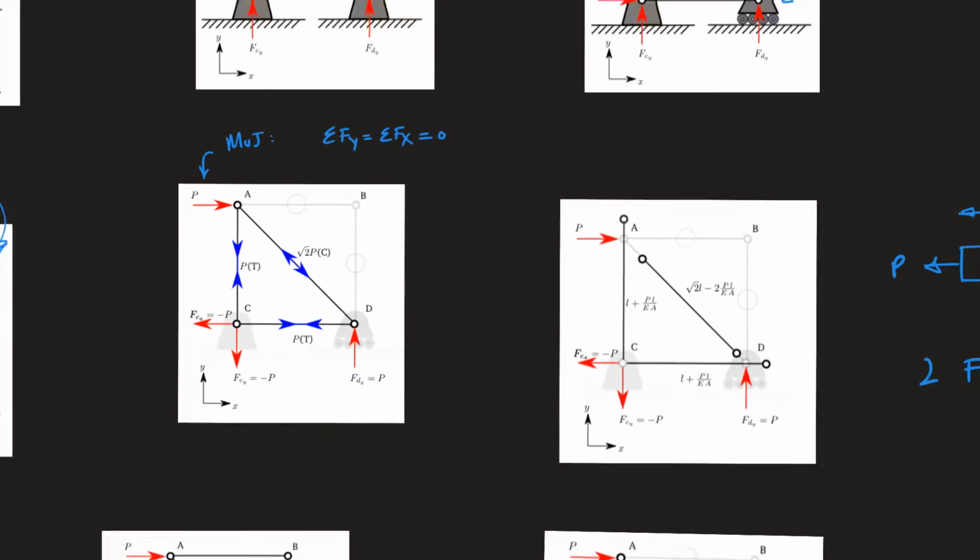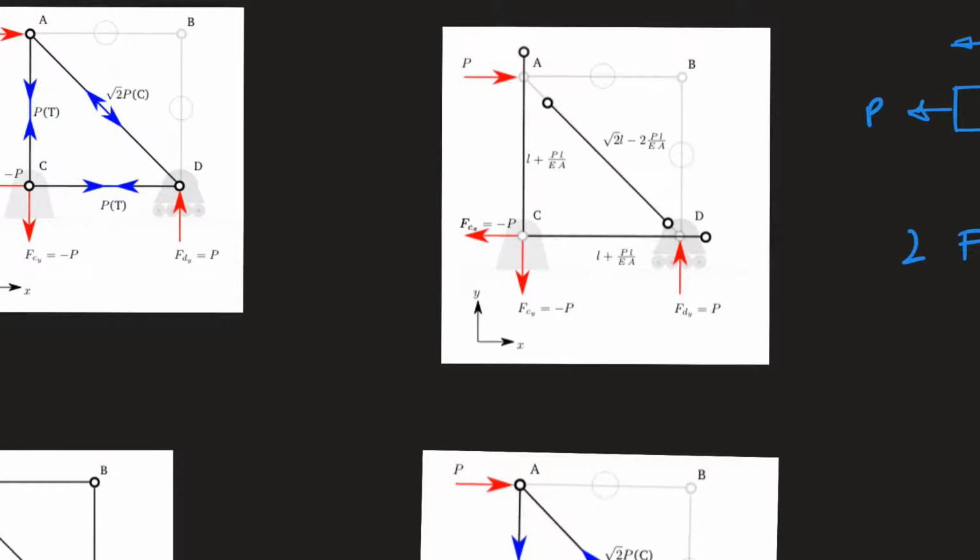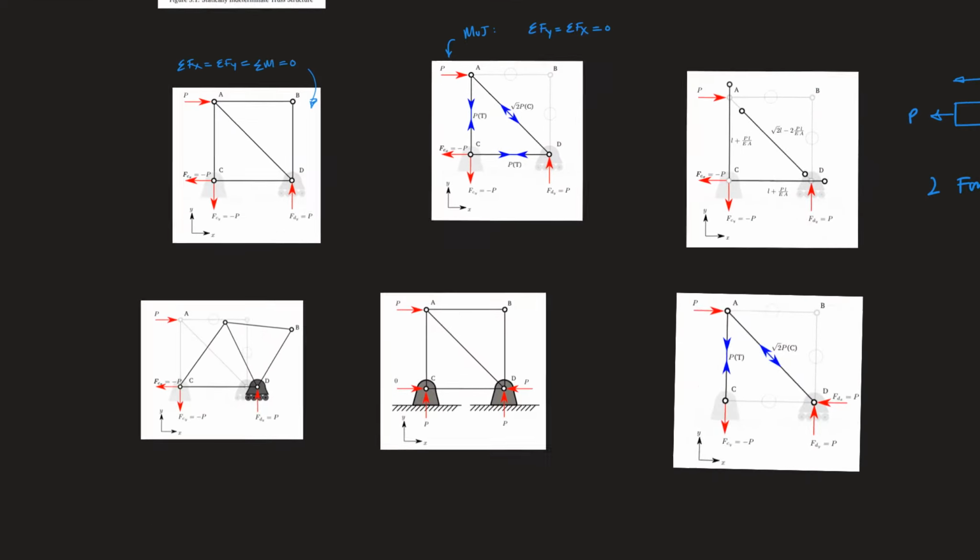So for this member here, we could ultimately unpin all of these members, and then we could work out what sort of triangle they've got to be to go back together. And in the notes, I go through that in full. We could be smart really here, and we could say that actually the extension in this direction has to be equal to the extension of member CD. Okay, and we could work it out from that method.